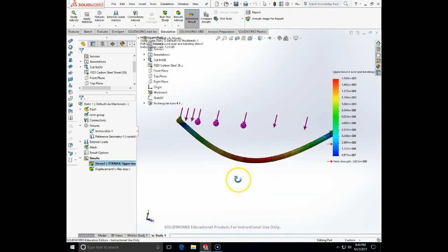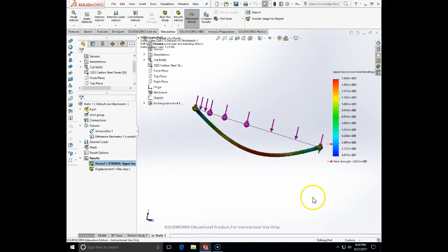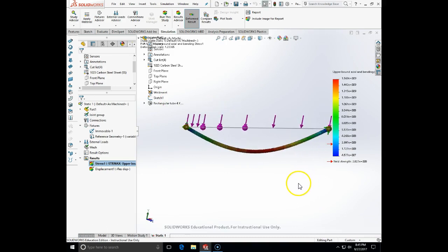And the first thing is just a common sense check. If everything is pushing down, obviously the beam needs to be bent down, and it should not be out of plane, or hanging on one node. So the first common sense check showed me that this model may be correct. So let's now check the beam diagrams.